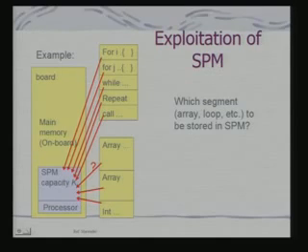That means the time taken for execution of the code is minimized. So I cannot put things blindly onto SPM. It is not like a cache. Please keep in mind, the problem is different. In case of a cache, when you make an access, that memory gets mapped onto cache, and you try to organize the data and instruction in such a way that cache hit is maximized. In fact, we had discussed this point earlier.